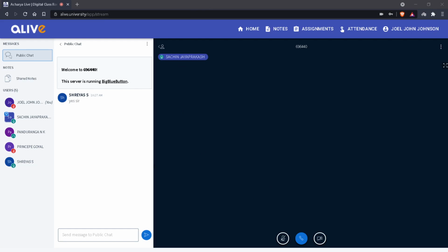But here it is generated automatically. And in case in the middle also, if you want to give some relation, let's assume this particular point I want to put in the center. Again, select this, select the midpoint which is here, and coincide, and enter. Okay, so now it is done.